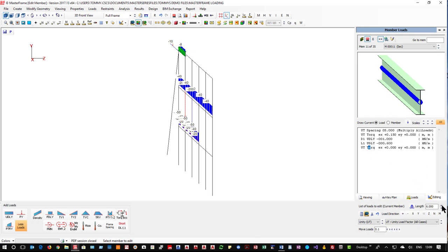So what I would do for good practice is say that this dead load of 1 is applied eccentric, whereas the live load isn't. Naturally, in this example, with the frame spacing, that doesn't quite make sense because you would be multiplying it up by the value at the same time. But where you do have wall loadings, the torque is a very useful tool to actually get that.